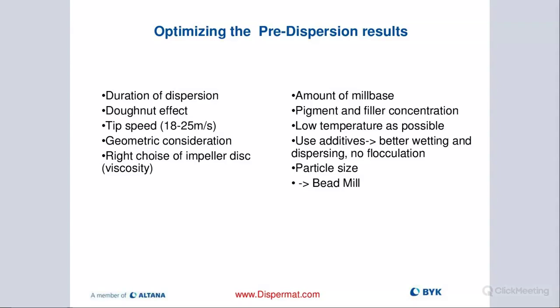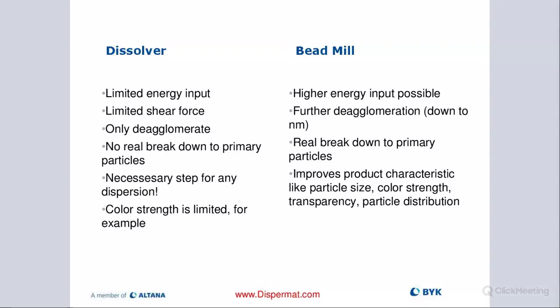And again, additives are really critical, helping us smooth out the process and keep these products in a suspended state. Really important during the milling process that we have a really high quality additive. And then right particle size, again, 10 to 30 micron. It's kind of like the rule of thumb. And that's when we then start the milling cycle.